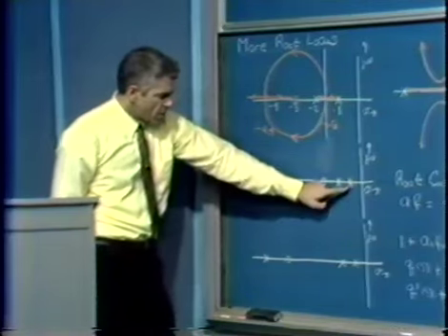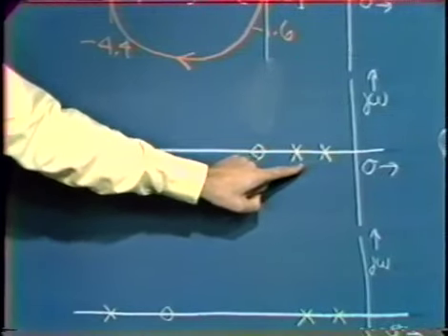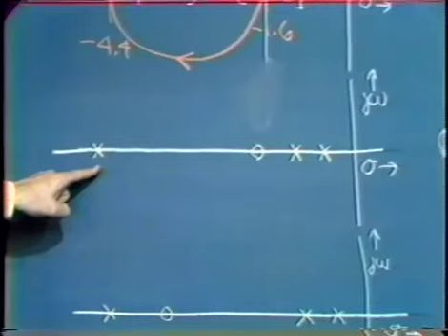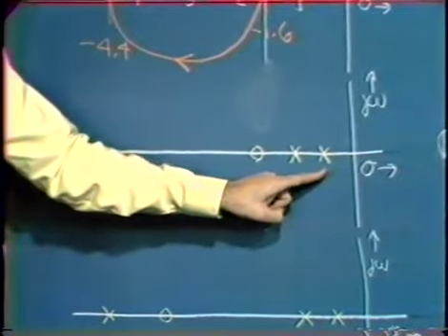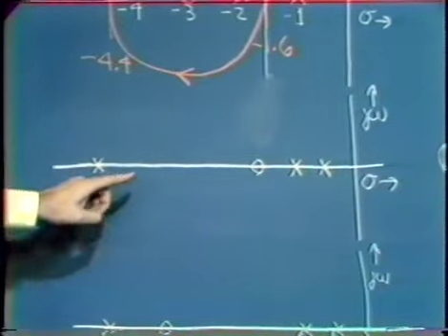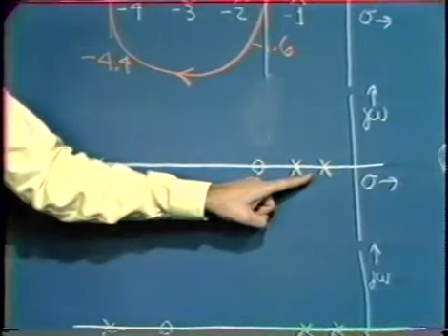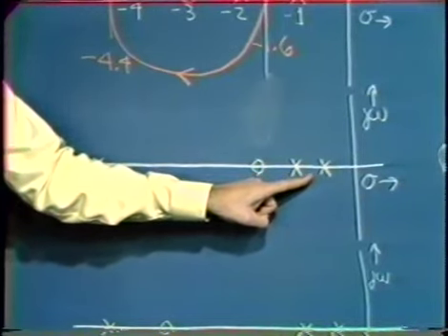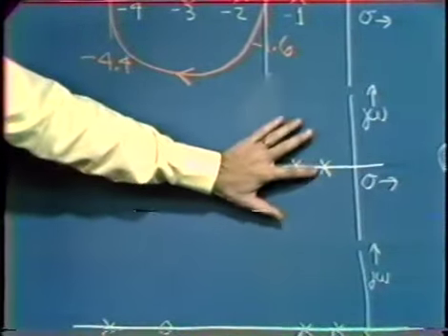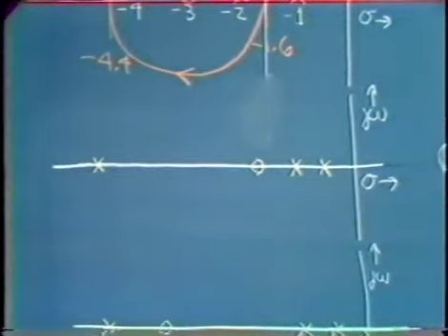Here I've shown another one where we assume we start with 3 real axis poles. Again, we did a calculation concerning this last time, and the numbers, of course, are dependent on the exact locations of the real axis poles, but we did a calculation where we had one pole at -1, one at -2, one at -10, and we found out that we could get very small amounts of desensitivity before we began to run into a stability problem. For example, we found out that the damping ratio of the closed loop pole pair closest to the origin got as low as 0.5 for an A0, F0 product of only 2.2.